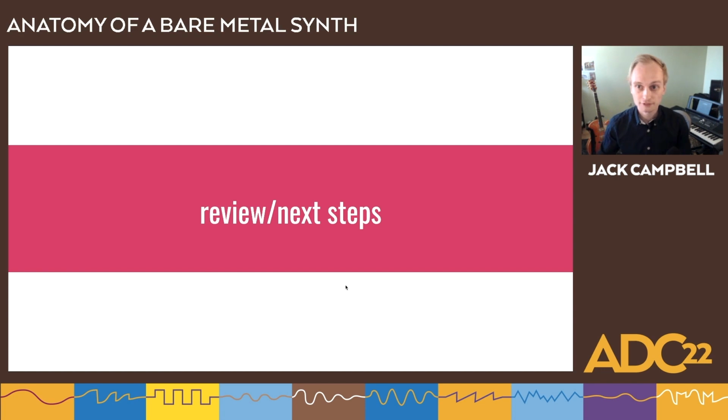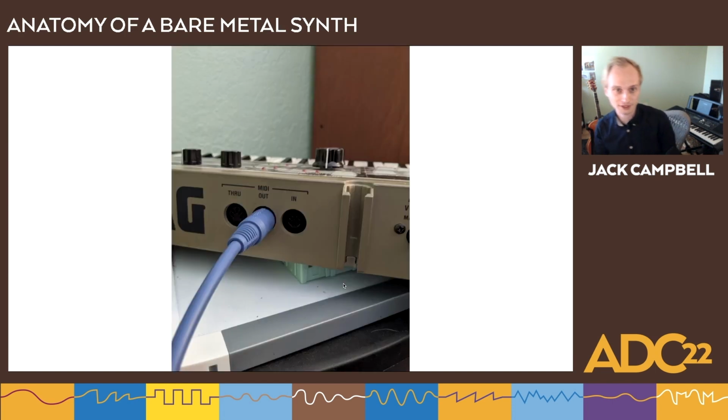So, it's got some artifacts there, especially if you had things turned up. But for 200 lines of code, it's pretty nice. Some sources of noise you'll find out, just as an aside, when debugging that noise, sometimes it's in the analog realm. The other day I had the noise that you heard there at the end of that clip, but it was really loud, and I was able to fix it by just changing how ground was configured. It was over all these wires, and dealing with that stuff and debugging it is very different from native stuff, and it's a cool little mind game.